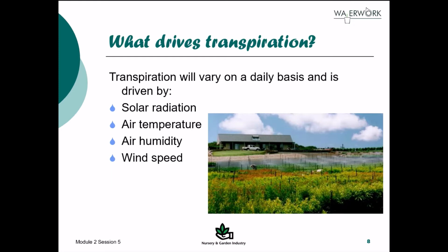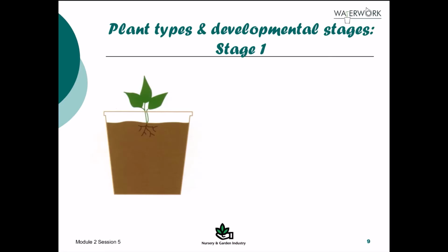For humid conditions, the wind can only replace saturated air with slightly less saturated air, and consequently for a given wind speed, high humidity will affect evapotranspiration far less than a hot, dry wind. Different plants will use different amounts of water. Generally, water use will be less from plants with small, narrow and sparse leaves than from those with large, broad and numerous leaves. The difference could be as much as threefold.